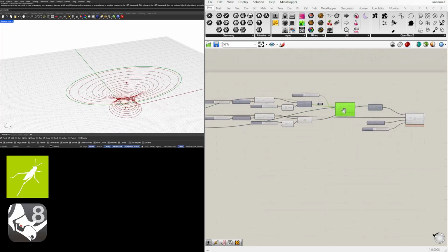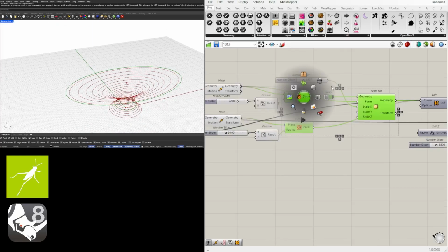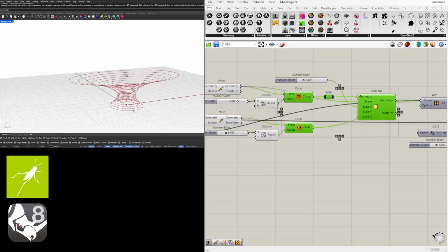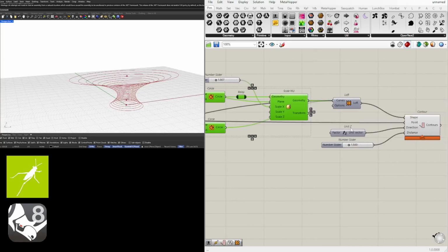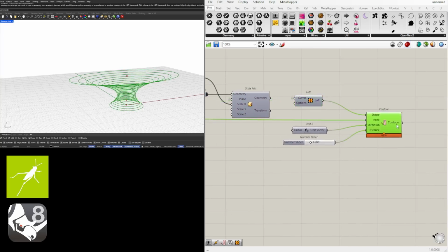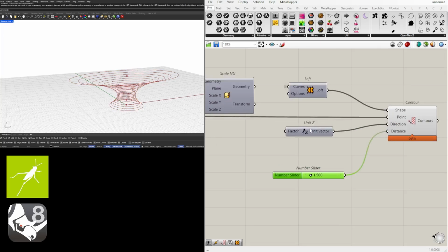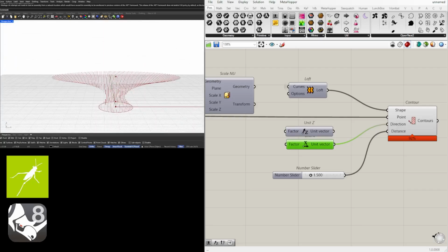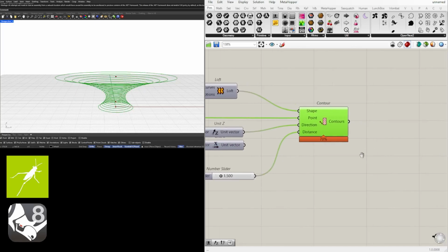Also hide all of these circles because now they're old as compared to the new contours, which define the same loft vertically. Now we can do the same thing in the X direction. If you wanted to change that, we can create a custom vector or just use the XYZ vectors, and this will create another type of design. But for now, let's focus on the Z direction here.